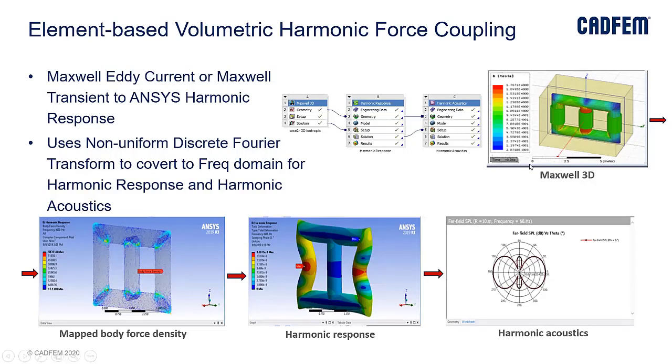You can see here, as I mentioned, it's the same platform we are using, the Ansys Workbench. Initially in Maxwell 3D we are doing this electromagnetic simulation and computing the volumetric forces, and the force density will be mapped to the mechanical model of the core. And here again, we are computing this harmonic response spectrum. You can see the deformation scale. Of course, here the scale is very high. We have made it very high, so that's why you can see this much variation. So this is about the volumetric forces coupling to the mechanical. Hand over to Tanakus.